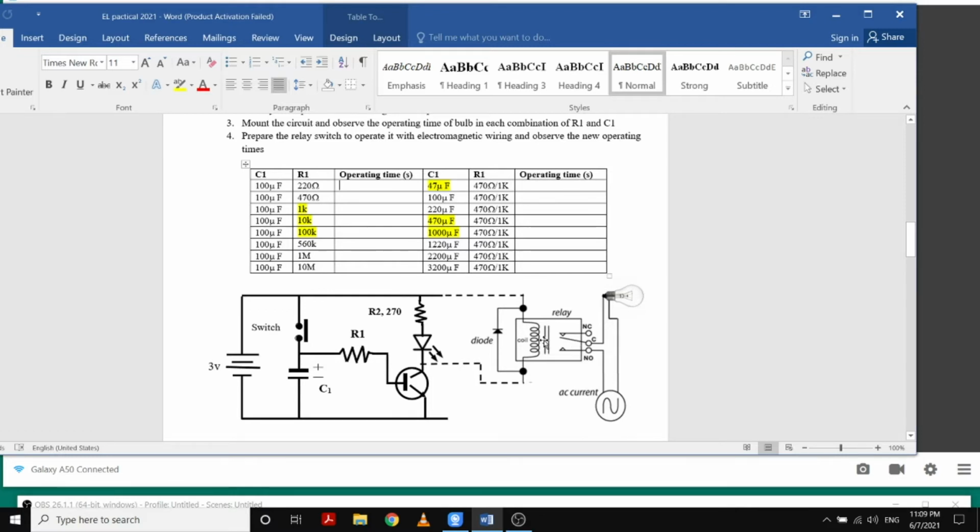So these are actually mechanical items. When it happens, it happens at once, right? So therefore you can see only two states, whether the metal plate is in this connection or this connection, right? When the metal plate is in this position, in this arrangement in the relay, the bulb will not light, right? When this coil gets electricity, this lever will be pulled to this side, so then this connection will be established and the bulb will light, right?